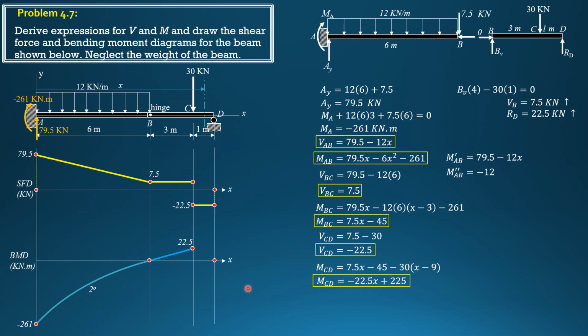So that's it. And if we are obliged to draw the elastic curve first, the tangent here is horizontal. This is the curve for this portion. It is concave down, elastic curve. Then in this portion, concave up. So it should look like that. Elastic curve. Concave down, then concave up, passing through the support. So that's it for this problem.